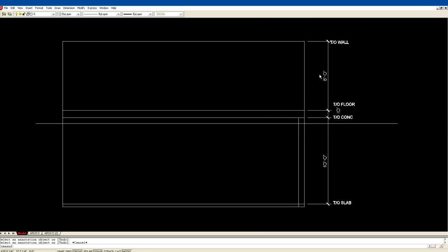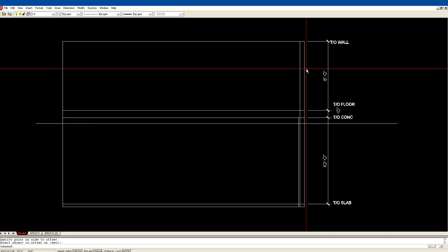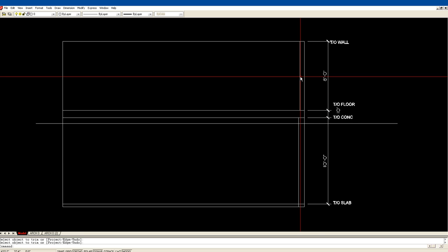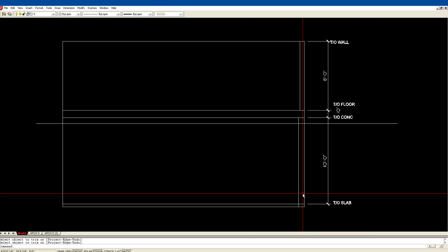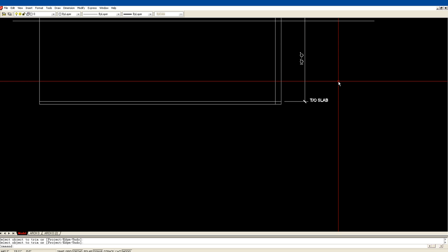Okay, so you can start to see, now we talked about the 6 inch walls. If you offset 6 inches and you trim, there's the wall, 6 inches thick on the top. Here's floor. Here is my concrete. Of course, underneath this concrete, to distribute the weight, you would have a concrete footing, and they pour it first. And typically, it's 8 inches thick, but 16 inches in width. And then it runs continuously underneath these walls.